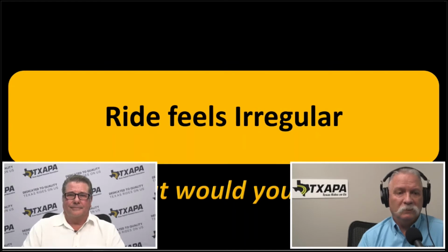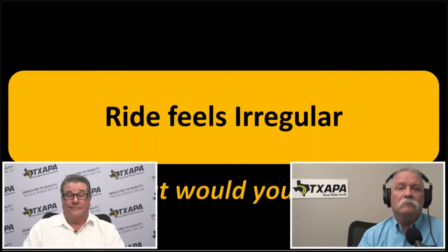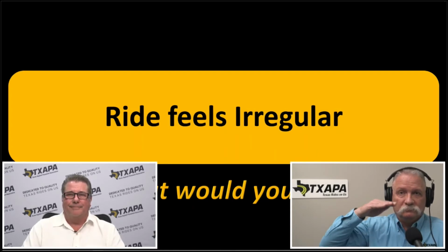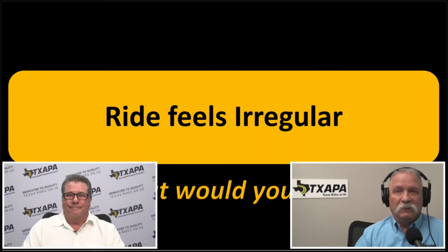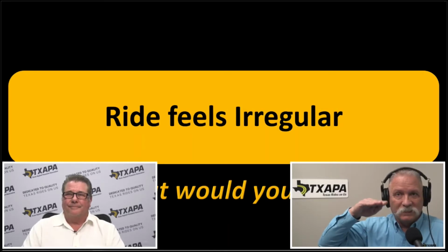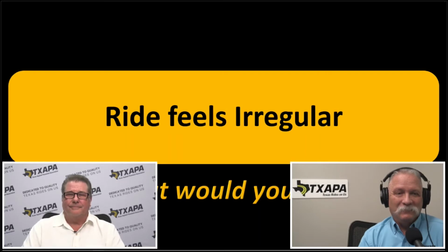Okay, good. And David Till. I will watch the breakdown roller, make sure he is stopping at a 45, because I've seen many a time he's not, and you'll never get that out of there. And it's consistent. About every 150 feet or so, you would have that same bump in there. The other thing I've seen was the sensitivity on your toe point. Seen ripples in there when I walked up and looked, and the toe point was moving up and down quite frequently. Yeah, if it's sitting still and just kind of shaking, we need to make an adjustment. That's a really good point, David.